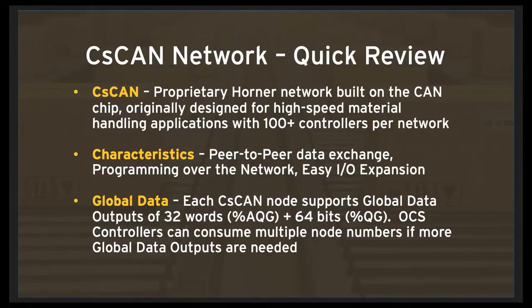It's got a lot of great characteristics, including a purely peer-to-peer data exchange, so it's not a master-slave protocol at all. You can certainly program over the network, and we demonstrated that last week by physically connecting over Ethernet to an XL7, and then connecting that unit over CAN to an XL4 and being able to program both units.